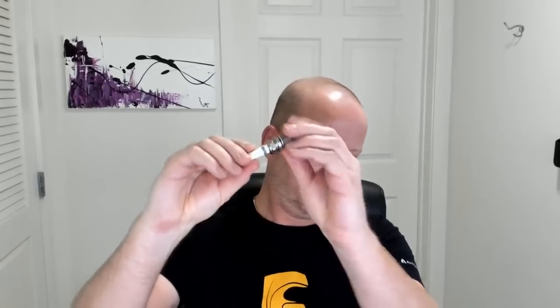So if it's in the machine and we're turning it this way, actually, I got that set backwards. If we're chucking on this side here, and we're turning here, and this is all thin over here, if we leave that thin, then when we're milling out here, I'm afraid we're going to get chatter. We've got to cut the thread. So we've got some features to cut here first.